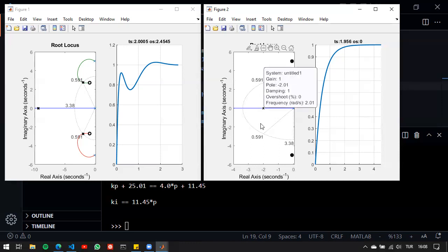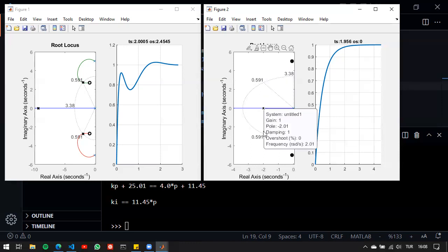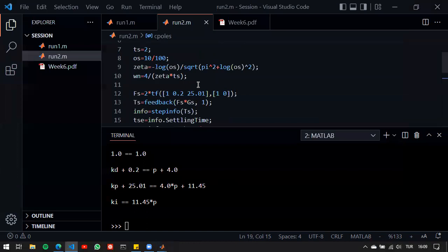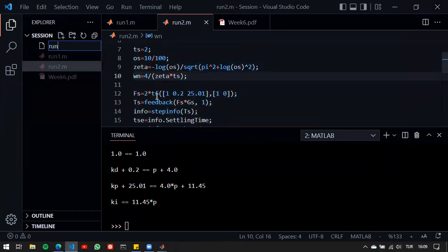And we can also directly conclude that we should add another pole at exactly -4, because we have only 2 poles. One of them is at the origin, the other one is at -4. So they will coincide at -2 and they will go up and down. So let's first try this and look at the results.